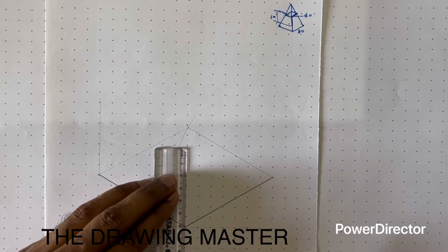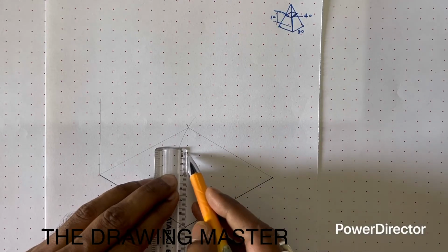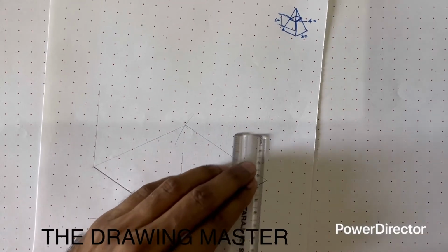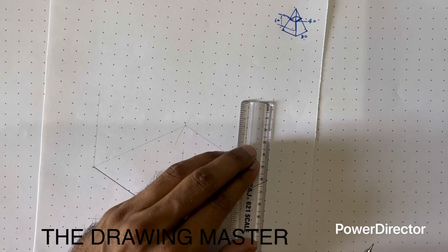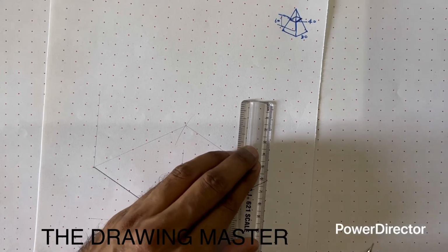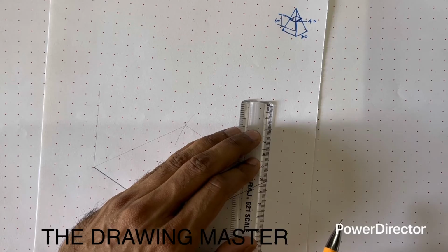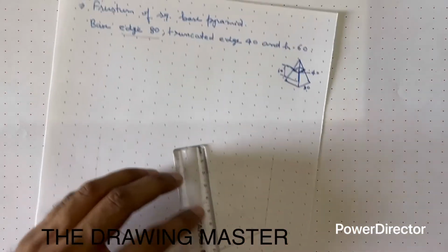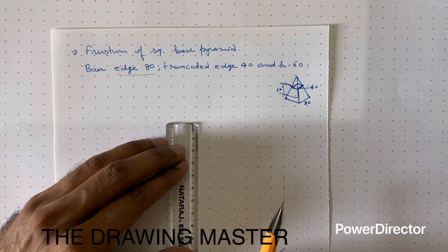These lines should be vertical lines. If a line is not vertical, the drawing is incorrect. From all the four vertices we'll measure the height of 60 mm. Now from this fourth corner also take the height of 60 mm.